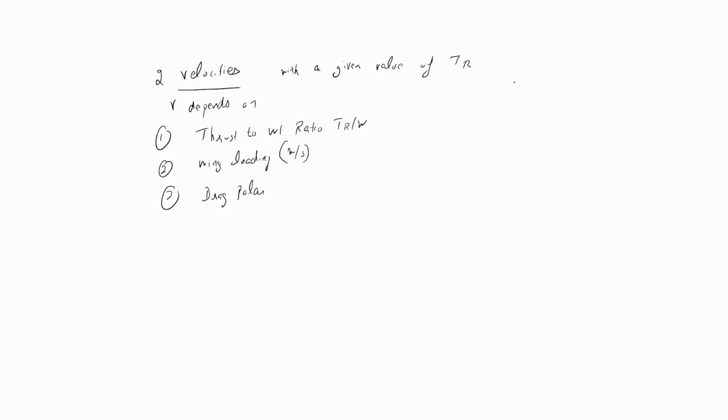So remember thrust required versus velocity. This is the curve. As we have seen here, it is giving two velocities. So one thrust required corresponds to this velocity as well as this velocity. And this is of course the thrust required minimum, the velocity at which the thrust required is minimum.